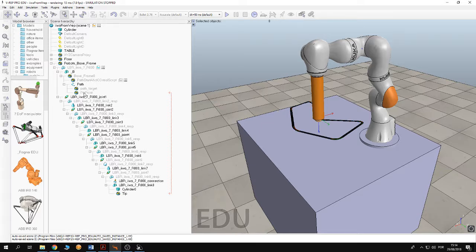So what happens is, when MATLAB gives a velocity to the path point so it starts moving on the path, Vrep starts to calculate the joint angles automatically through its inverse kinematics solver. Now this inverse kinematics solver can be found in here.